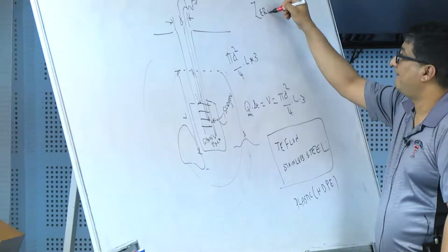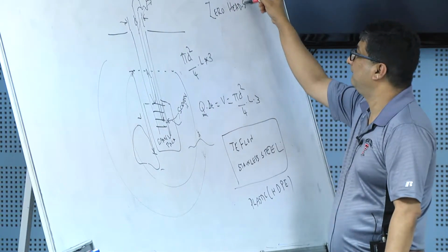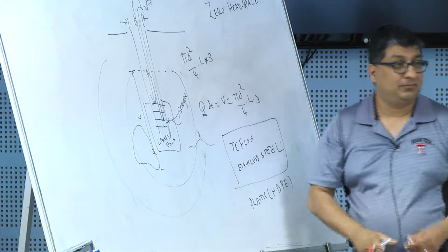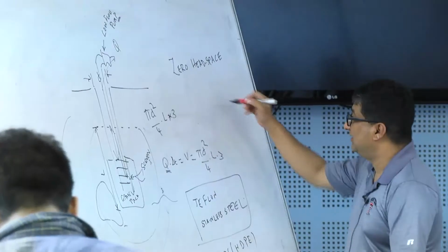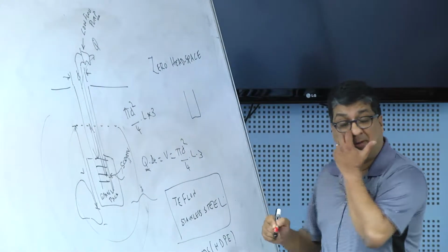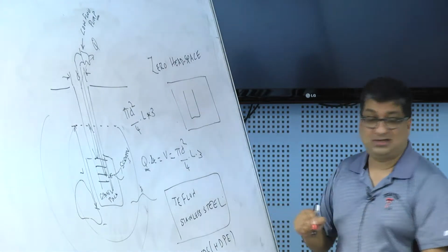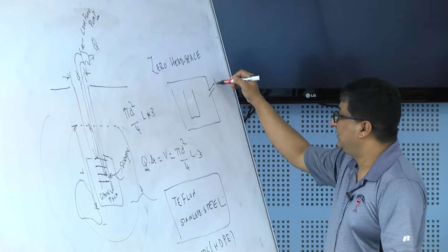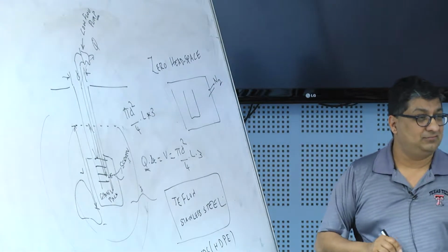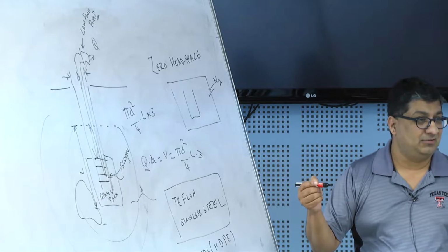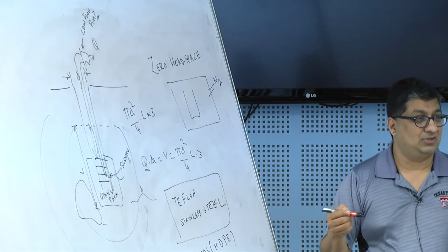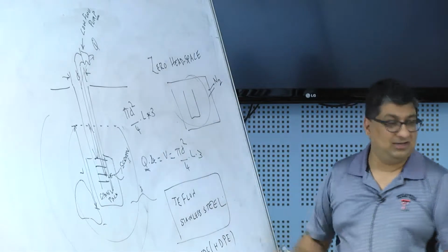And the second thing is when you collect volatiles, usually we do what's called a zero headspace sample. Back in the day, we would essentially take a chamber, connect it to nitrogen, and purge it with nitrogen, and we would remove all the oxygen in this chamber.